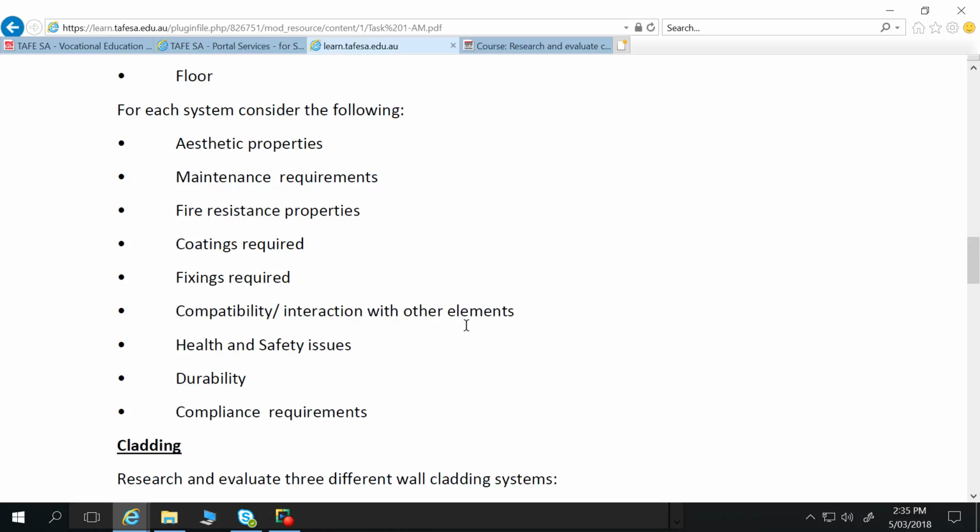So the steel shell of the tank we build, it's a mild steel basically, but then we put on a magnesium bar that's attached by a wire. Magnesium is a far more reactive metal than mild steel. So when the two are joined together, all of your free electrons in your magnesium grab onto oxygen, and then that takes free electrons from your mild steel, and so your mild steel doesn't have any free electrons anymore to bond with oxygen, because that's what rusting is. It's the bonding between steel and oxygen, or any metal and oxygen, that causes rust.